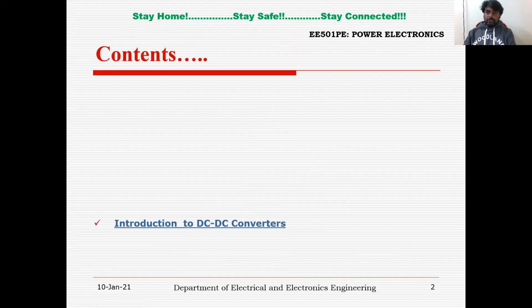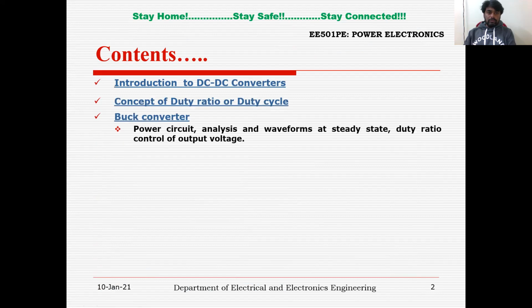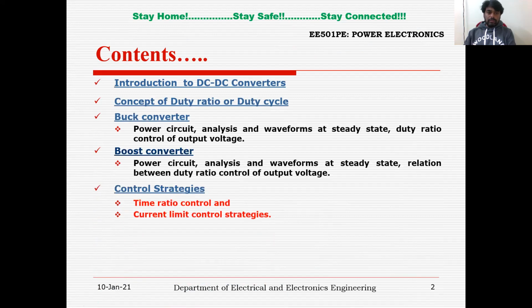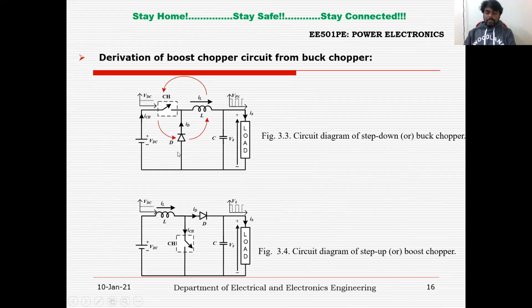In this video lecture, I am going to explore the boost converter, which is also called the step-up converter. In my last video, we discussed the buck converter or buck chopper, which means the output voltage is less than the input voltage. And here you can see the configuration of the buck chopper or step-down chopper.